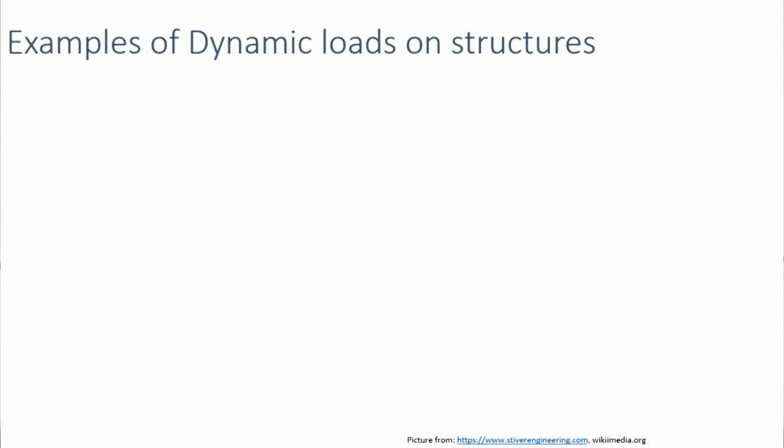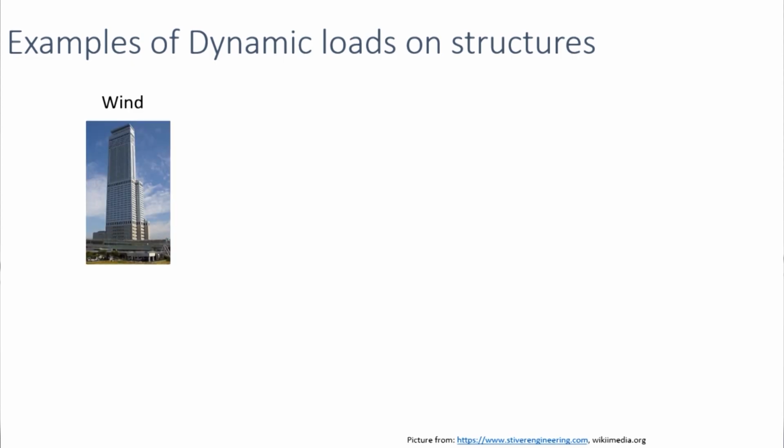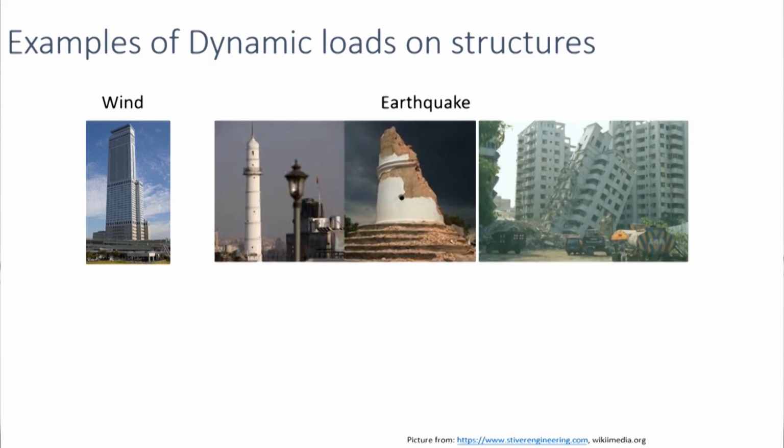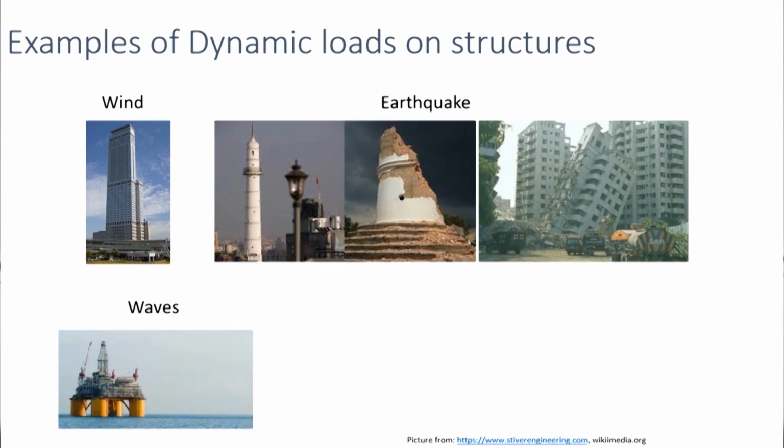So now, let us look at some examples of dynamic loading on structures. First, we have wind loading. This is very predominant in tall structures. Then we have earthquake loading. This is very critical and very damaging. Offshore structures experience wave loading, which is also time varying in nature.